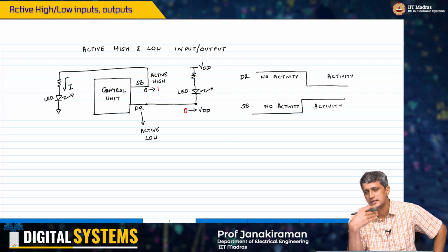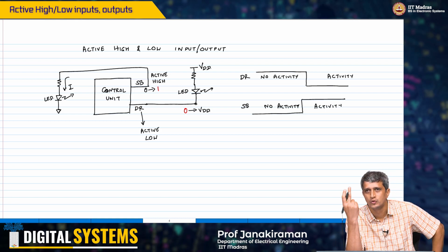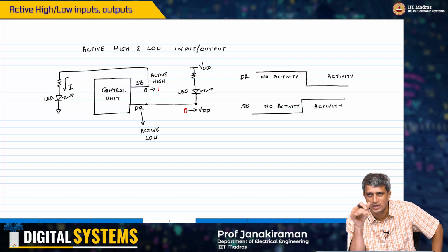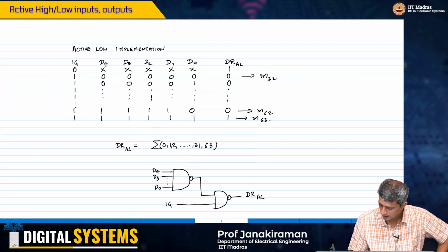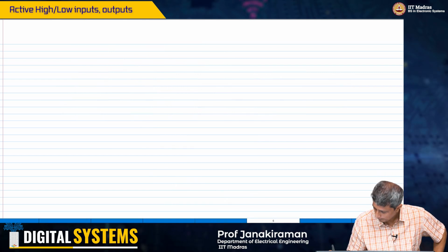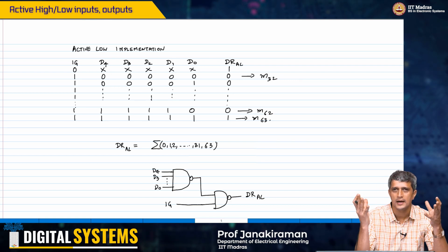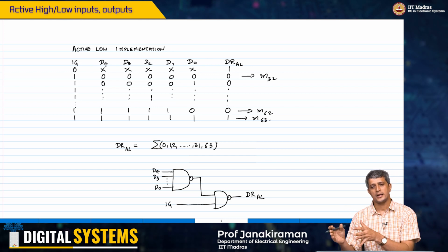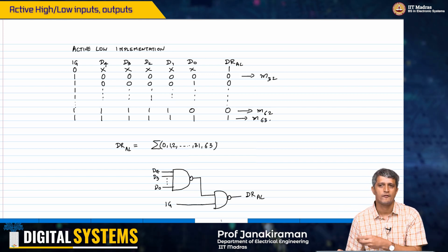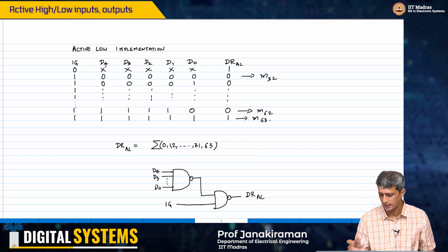Okay, like I told you, in this case the LED requires, you know, some LEDs you might have to connect to the supply, in which case the Boolean logic will have to drive it low. Okay, so you will have to appropriately design this particular logic accordingly. Okay, so that is the overall idea of how we started with a problem in the English language and translated that to the truth table and effectively into the gate level implementation of these things, right.